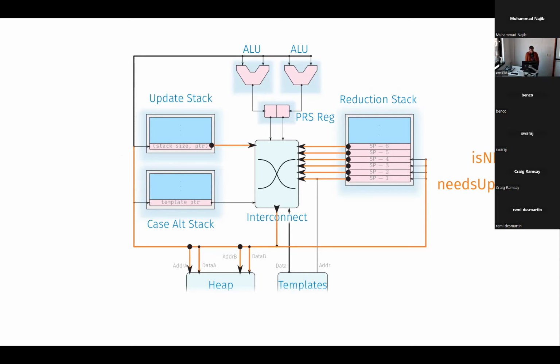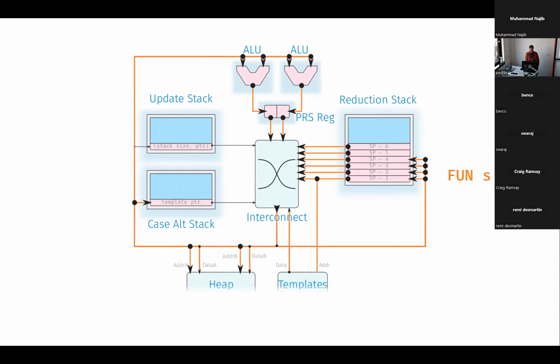But the only kind of interesting operation here, the fun one, is doing the function application, in which we touch nearly every single memory in the whole system. So instead of using very complex pipelining to keep all of our different units busy, with function application, we've just designed it so it will need to touch every single part of the system anyway. And constructors for us, because the way we've set up the case alternatives as functions, that's kind of just a special case of function application.